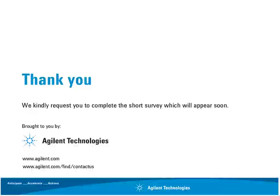Okay, thank you. And one more question for you, Scott. How do I know what detector and averaging type to use when measuring a signal? When measuring CW signals, you would want to use the peak or the normal detector. However, when measuring noise or noise-like signals, then you would want to use the average or the sample detector. However, be careful when using the sample detector because you don't want to miss a CW signal, so just ensure that your resolution bandwidth is greater than the span divided by the number of trace points minus 1.